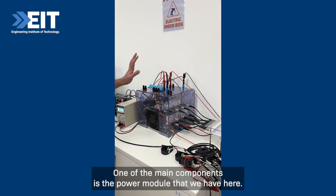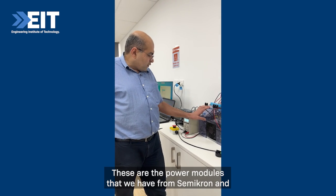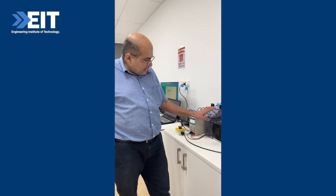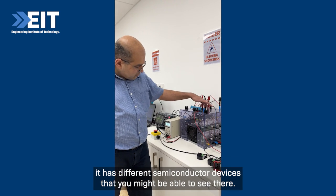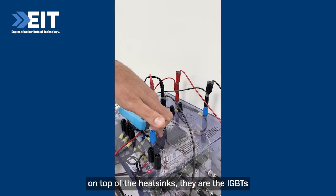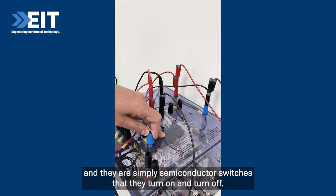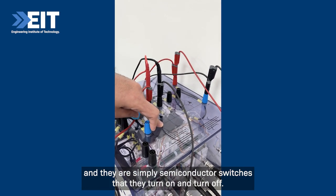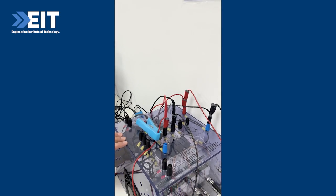It has different main components. One of the main components is the power module that we have here. This is the power module that we have from Semikron, and it has different semiconductor devices. You might be able to see the white blocks on top of the heat sinks. They are the IGBTs, and they are simply semiconductor switches that turn on and turn off very fast, at high switching frequency.